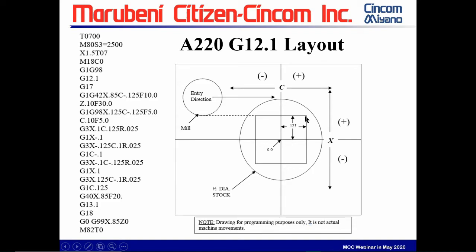If you notice, that is in the drawing like a clockwise move, but it's G3 because it's reversed. But it's going to an X.1 here, generating a 25 thousandths radius, going to these two positions. Then it goes down to 100 here. Again, G3 to this point here, generating a 25 thousandths radius, and so forth. But this is an example of it using G3 to go around the outside of this part.